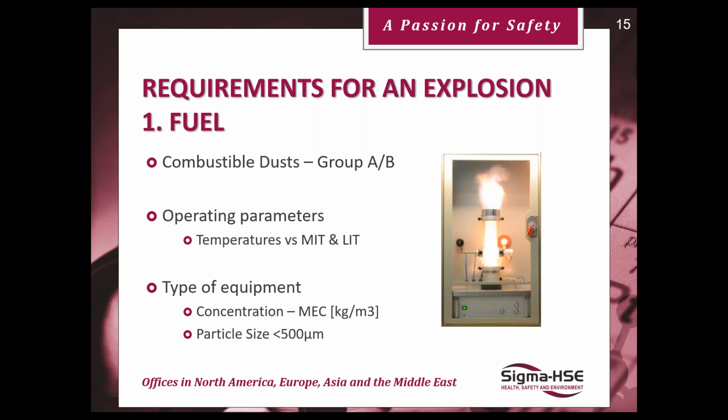So we've got to have sufficient dust in the air, and to be able to get that powder into a dust cloud so it's dispersed in air, we're really talking about the dust. We're talking of particle sizes less than 500 micron. If you're dealing with granules and things like this, very little dust present, again, the combustion reaction shouldn't occur because we can't get sufficient fuel into the system to make it explosible.